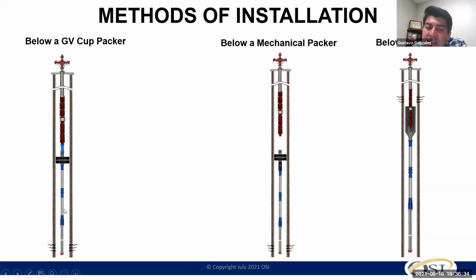So the sand has to go to the sand screen, and at that point, you are controlling the amount of sand that is passing through. Or if you put a combination with a desander underneath it, you are sending a portion of that sand through the tailpipe. But to be 100% honest, you cannot separate or filter 100% of the sand. If you do that, you're going to plug the entire system and you're going to fail.